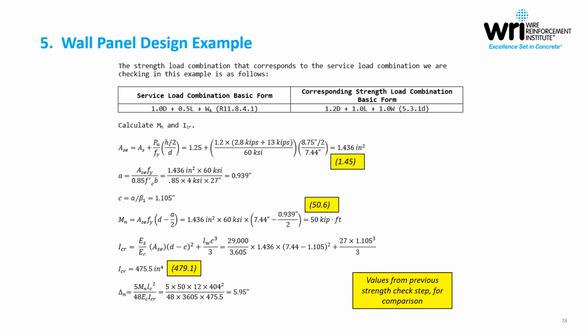So some designers will elect to use the full equation, which would include L sub R. This is of course a decision that would be made by the designer on a project specific basis. So the yellow values that I'm showing here are what we used in our previous strength calculations. You can see they're close, not precise. Some might argue that this is an extra step that might not be worth it, but I did want to go through this to show that it is sometimes done.